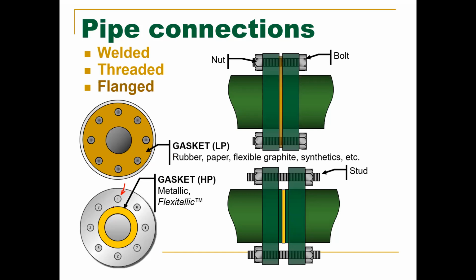You don't always have to start at the top. If you want to start at number 8, start at number 8, but then number 8 becomes number 1. Then this is 2. And then we go to 3 over here, 4 over here. So wherever you start, you have to follow this sequence. Otherwise known as a star pattern.